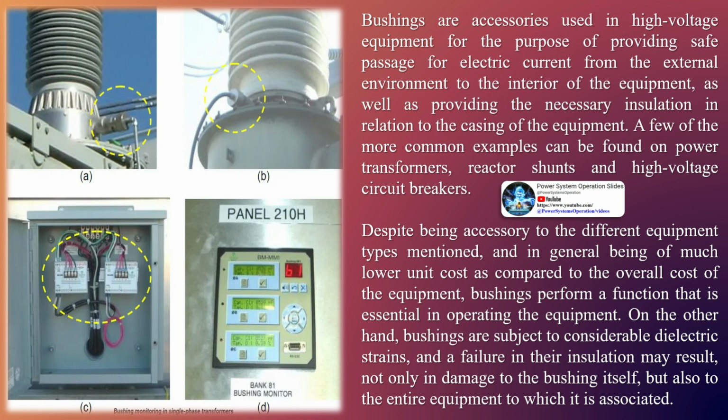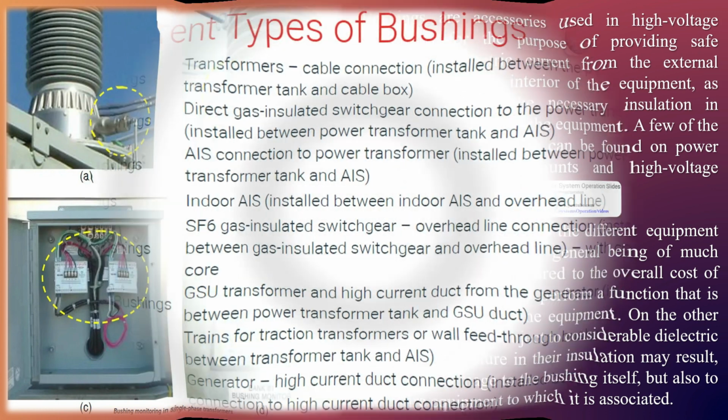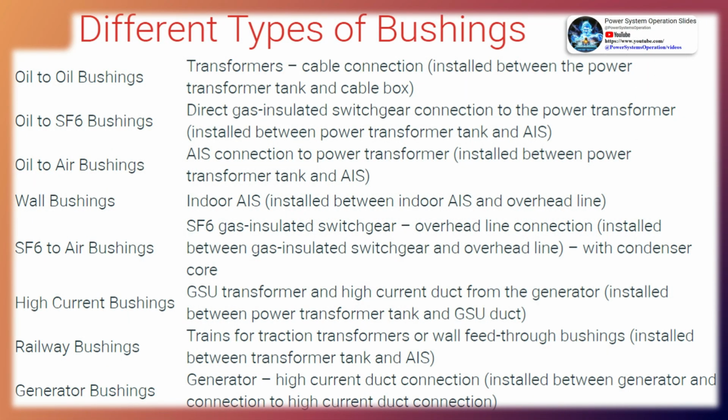Offline and online power transformer maintenance practices for bushings. There are offline periodic testing practices and online monitoring practices for transformer maintenance. The online continuous monitoring practice has been gaining traction due to high return on investment and effectiveness in not only avoiding failures but also reducing time-based maintenance costs. The offline periodic maintenance practice for bushings may include visual inspection, infrared inspection, cleaning using different methods, power factor testing (tan delta), and capacitance testing. Different types of bushings can be seen in this table.